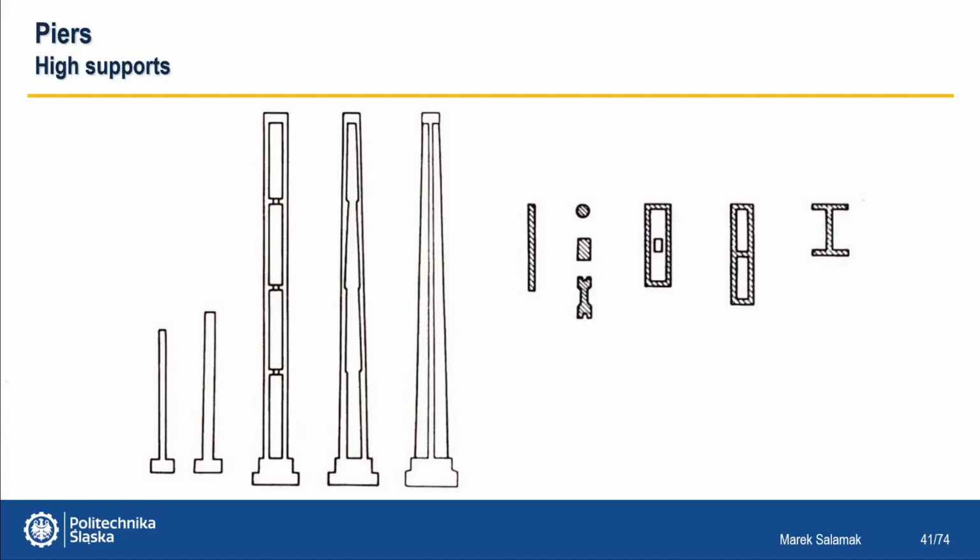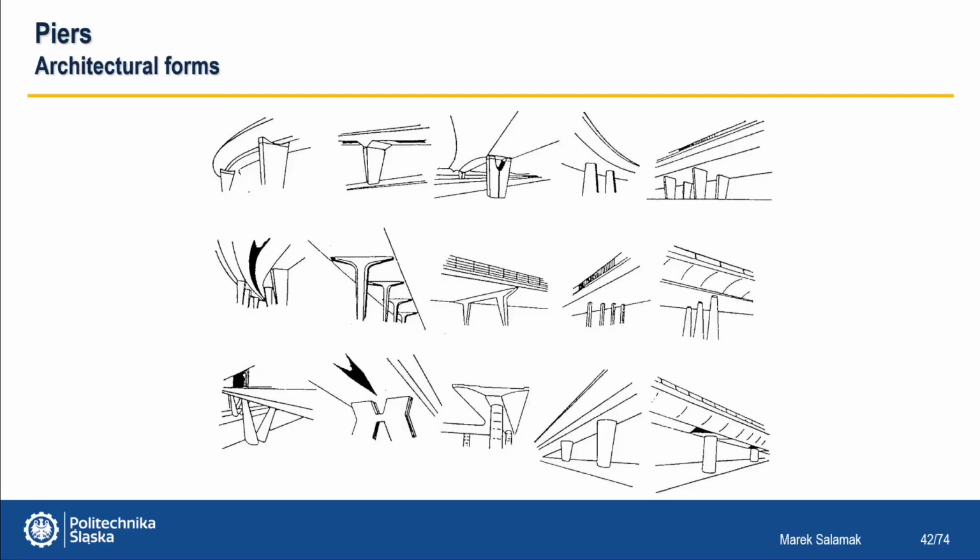For high pillars, full cross-section is no longer used. The interior is usually chambered and there are stairs for inspectors, bridge inspectors, or even elevators. The pillars on the city bridges also have an aesthetic value. Therefore, they often have to be refined in terms of their architectural form.